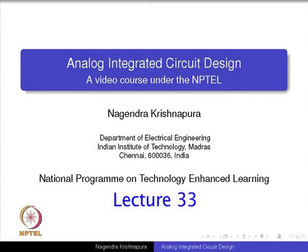Now, let us say I want a 1-to-1 current mirror, that is M0 and M1 are identical and I want I1 to be equal to I0. Then, it is very obvious that if I make MC0 and MC1 identical, they will have the same VGS at a given current. So, I will bias these two voltages from a common voltage VG0 that I will obtain from somewhere, and now M1 and M0 are identical to each other, MC1 and MC0 are also identical to each other.